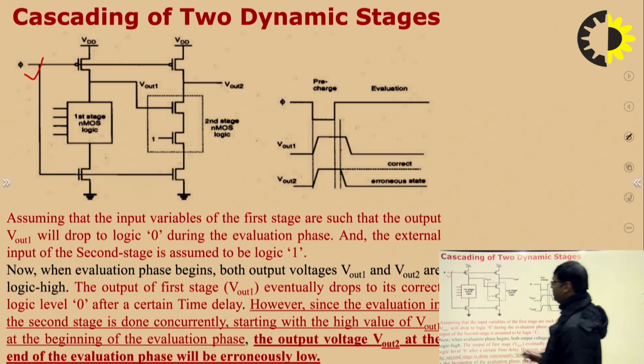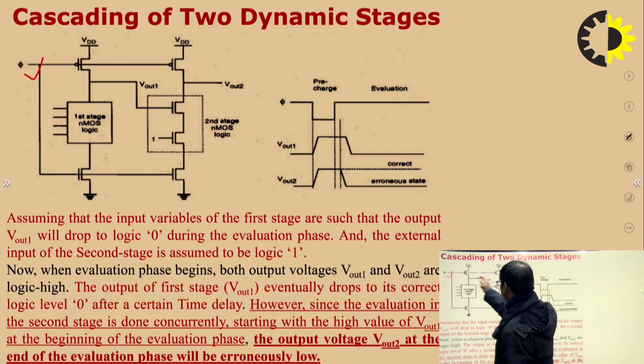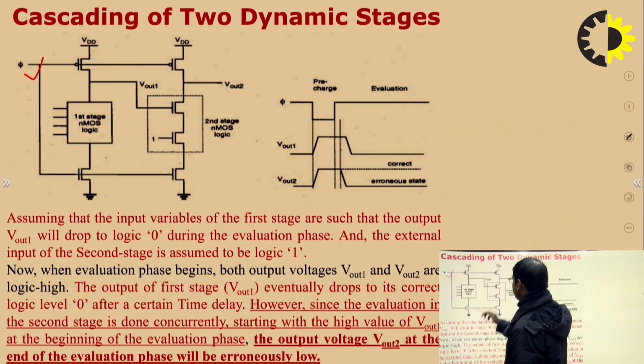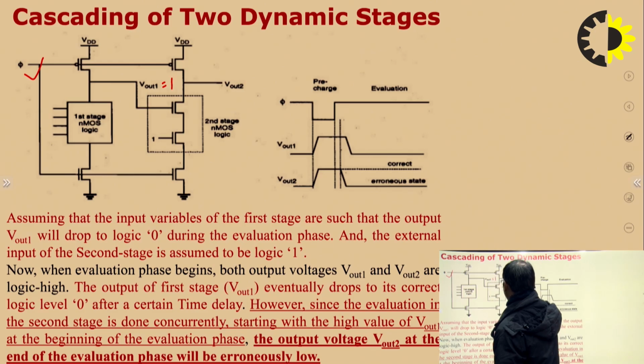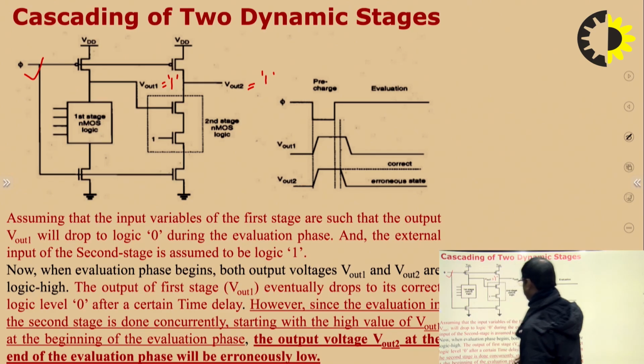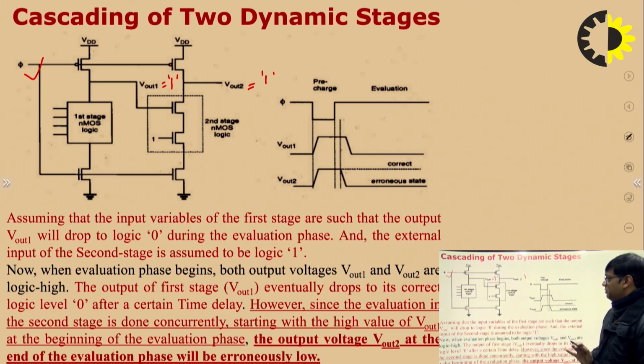At the same time, both these PMOS transistors are on during the pre-charge phase, and both these outputs Vout1 and Vout2 will be logic 1 during the pre-charge phase.